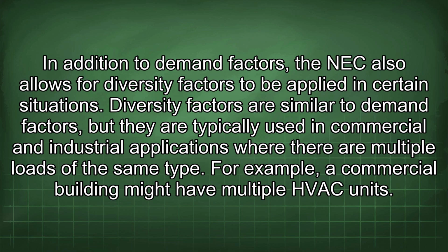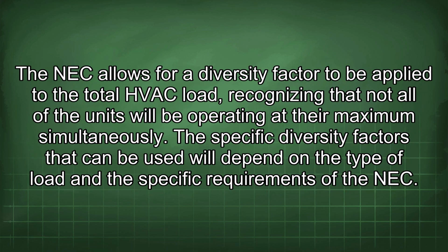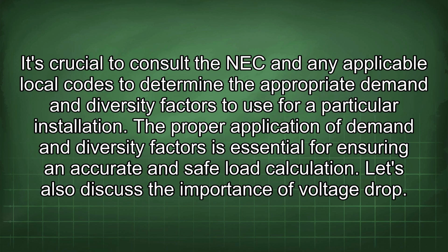For example, a commercial building might have multiple HVAC units. The NEC allows for a diversity factor to be applied to the total HVAC load, recognizing that not all of the units will be operating at their maximum simultaneously. The specific diversity factors that can be used will depend on the type of load and the specific requirements of the NEC. It's crucial to consult the NEC and any applicable local codes to determine the appropriate demand and diversity factors to use for a particular installation. The proper application of demand and diversity factors is essential for ensuring an accurate and safe load calculation.